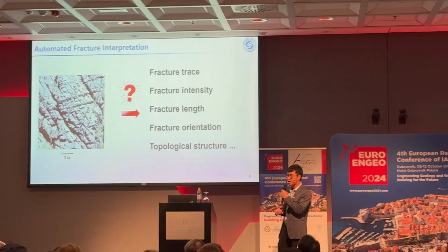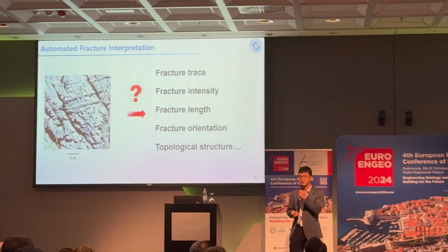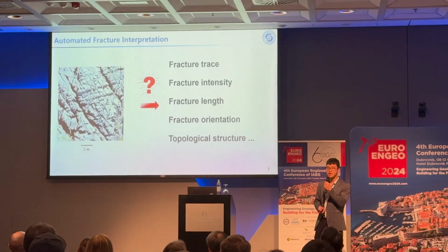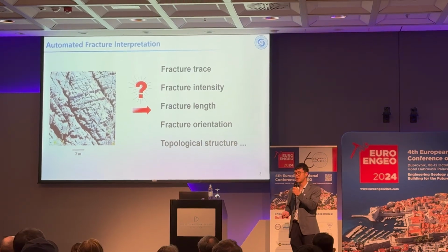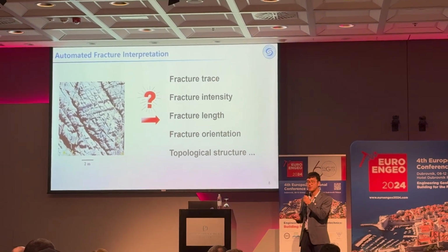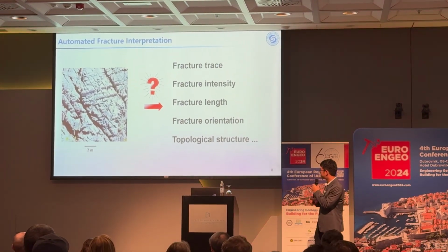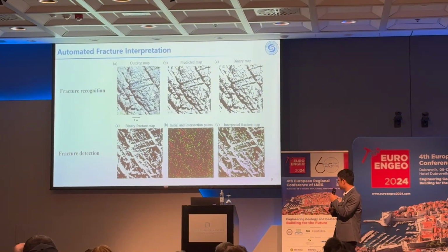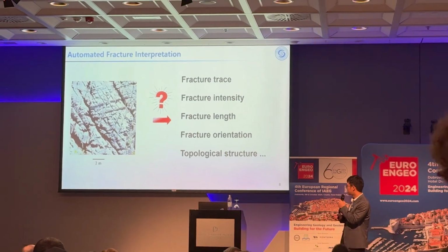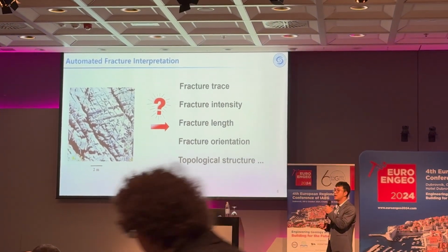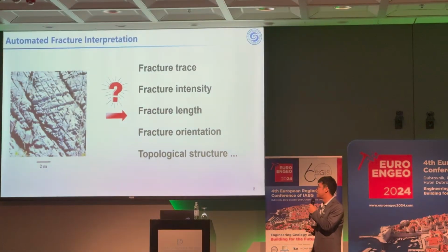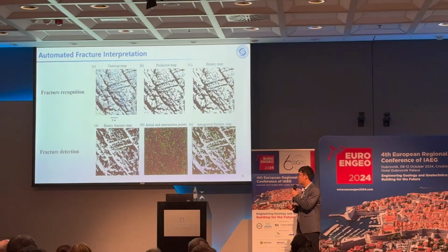So there are also challenges for outcrop observation, because it's easy to collect, but it's very difficult or tedious or time-consuming to interpret fractures from outcrops. For example, you want to have the fracture trace, you want to find the intensity, length, orientation, topological structures, all those things. You cannot easily find that. If you do it manually, it will be very time-consuming. So you want to develop a better way to do it